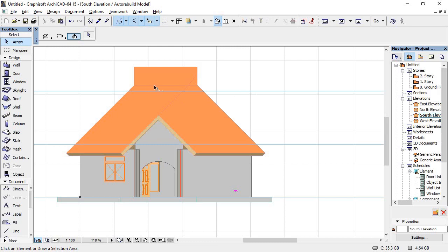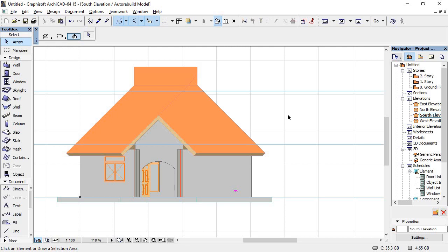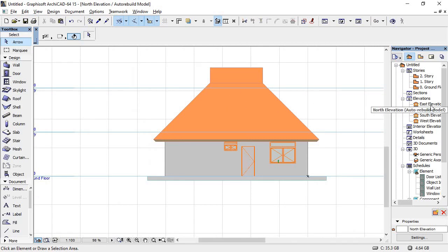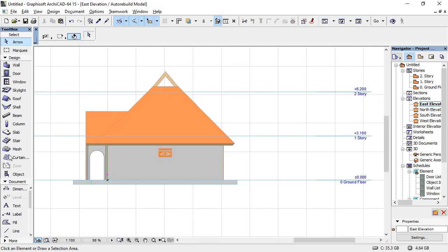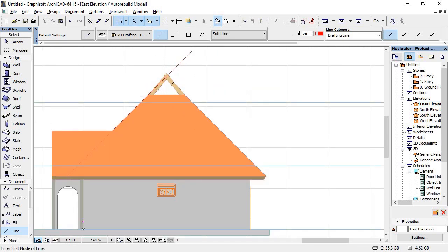Something also to notice is that this roof here is not straight, and we need to straighten it. How? What we are going to do is that from one of the sides, which side is this? This. I need to draw a very straight line from here, moving that direction. Press Shift to make sure the roof is moving straight. Now I need to do something here.